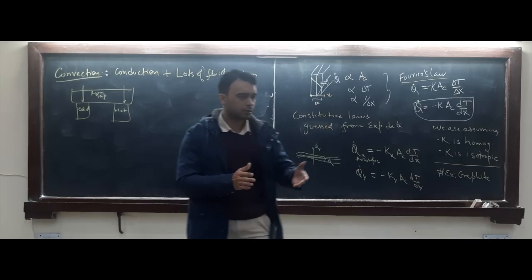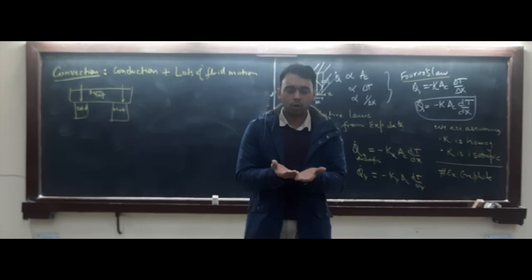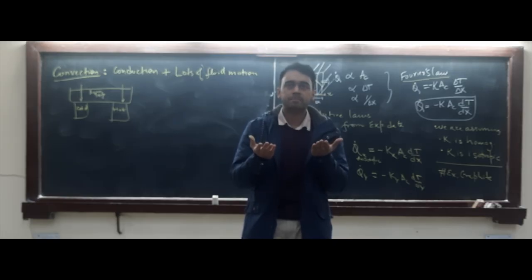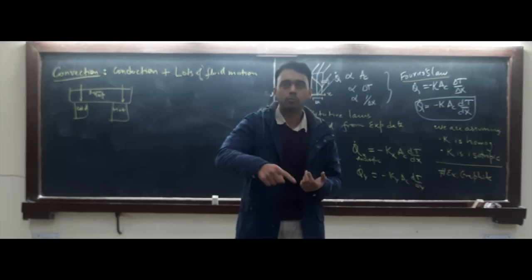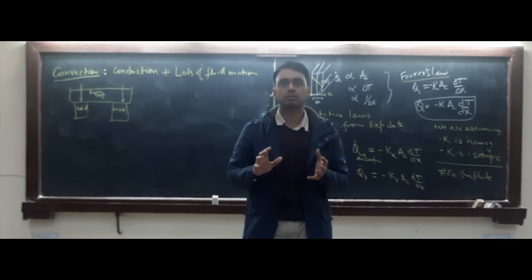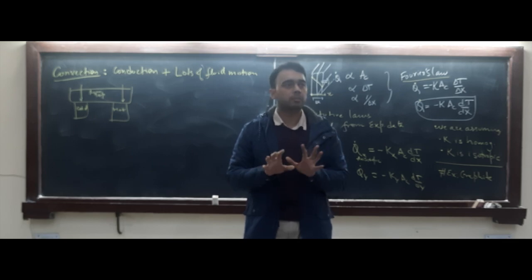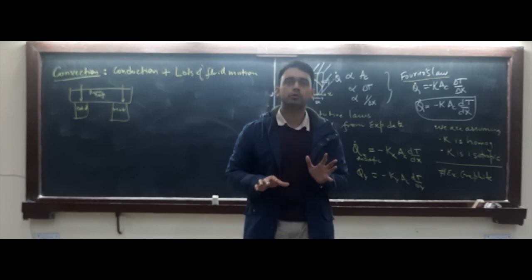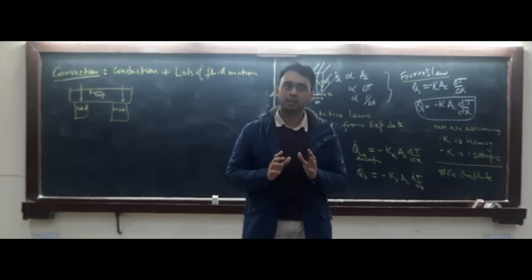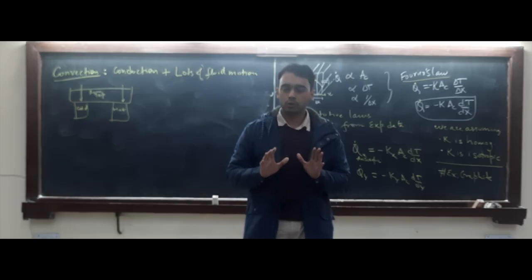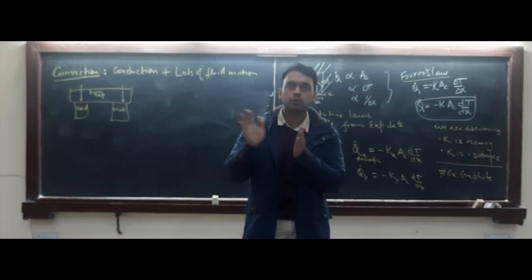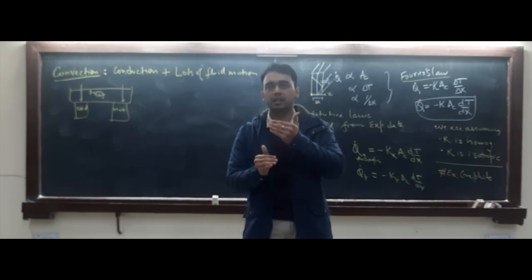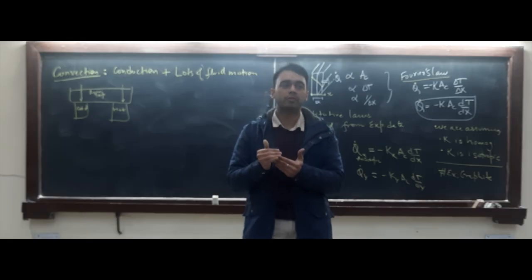Let's say, for example, what you saw there, the bottom layer is hot, the top layer is cold, and convection will take place. In this case, it's natural. If you were to dip your finger and move it, it will be forced convection. But in general, convection means fluid motion, and ultimately the fluid is exchanging heat. Why conduction only? What you are doing by convection is just bringing the cold and hot molecules together so that they can exchange heat more efficiently.